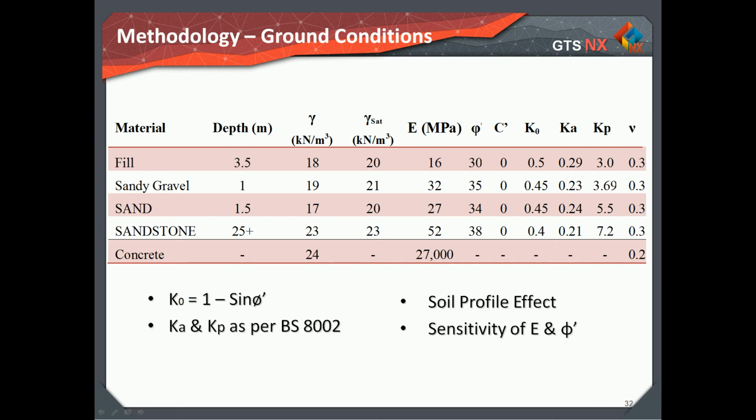The ground investigation report confirmed the existing ground in the vicinity of the attenuation tank consists of 3 or 4 meters of made ground fill on a thin layer of sandy gravel, on medium dense and undrained extremely weathered sandstone formation. No groundwater was observed on any of the 6 borehole logs, and therefore the water table is assumed to be well below the excavation level.